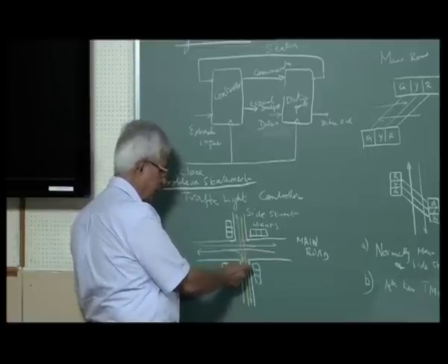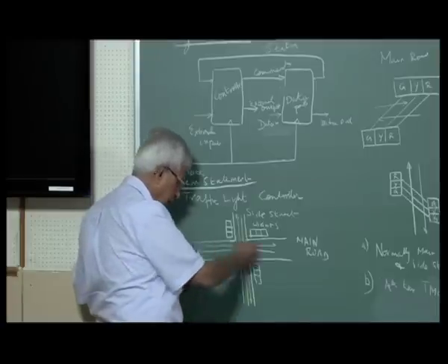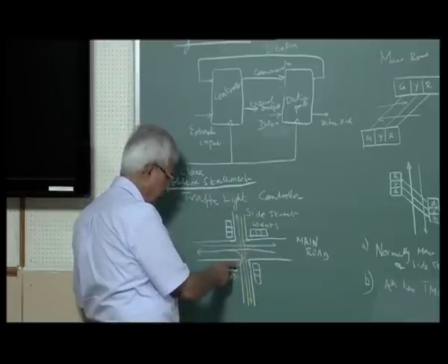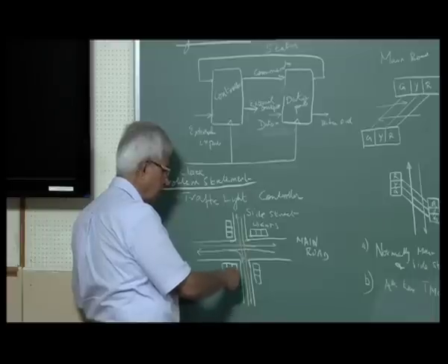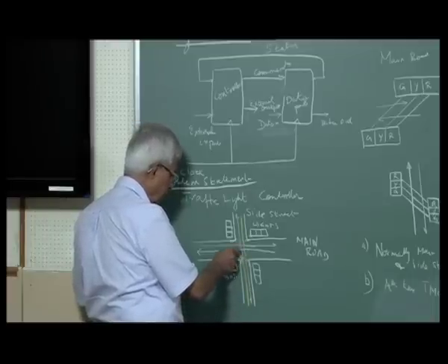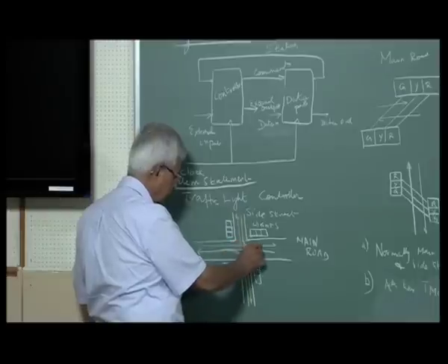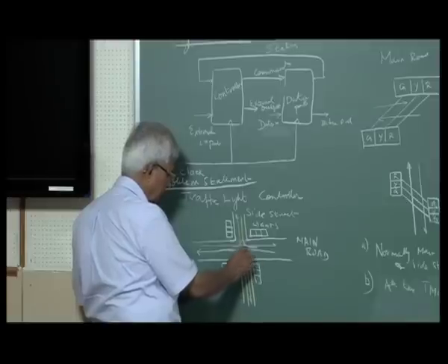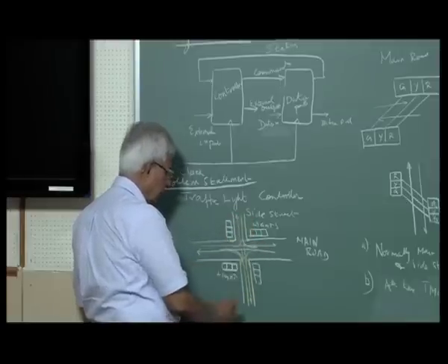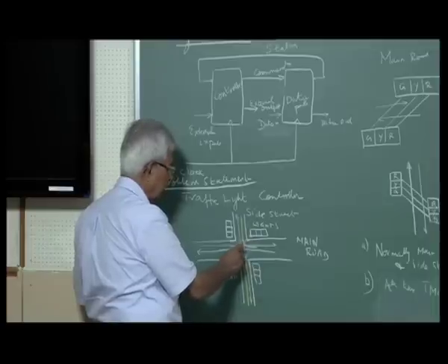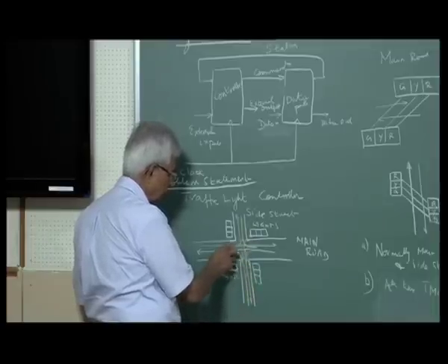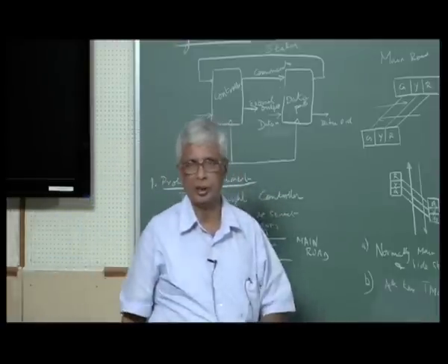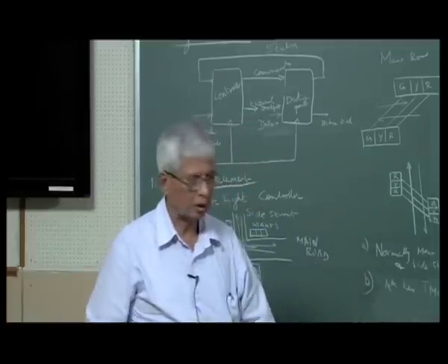I can introduce conditions like after the elapse of certain time, if there's no traffic, you can put a car sensor. If the car sensor is not active, there's no point in stopping the main road traffic. I can also have a pedestrian switch. If the pedestrian switch is pressed, it should stop the traffic. I can also say we are only able to turn left for now. I can also make turning right possible. In that case, the opposite traffic should be stopped. Similarly from here, turn right, opposite traffic should be blocked. All those conditions I am not putting now, in the earlier, simpler version.